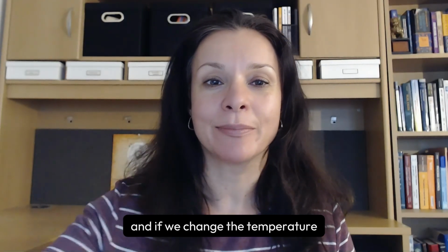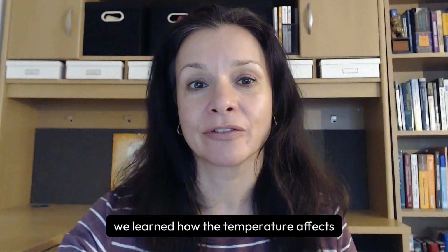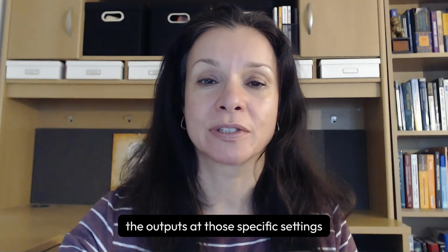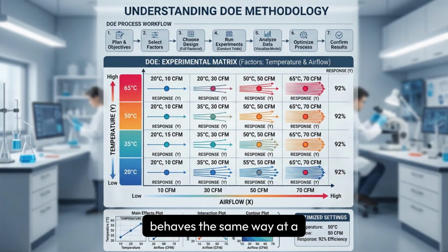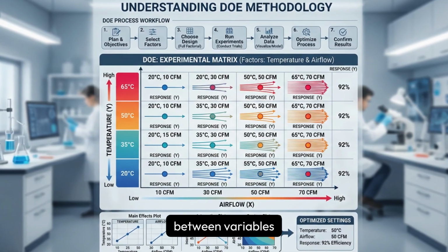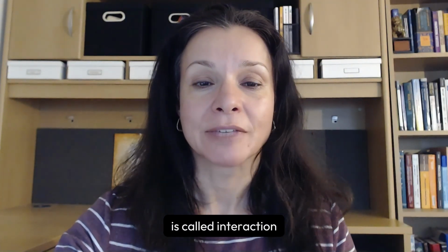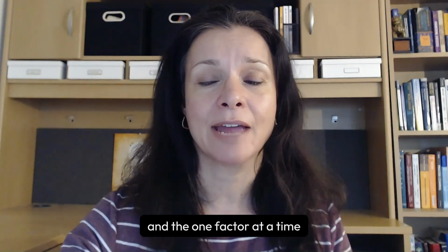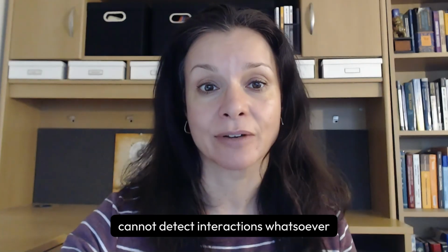And if we change the temperature while holding airflow and speed constant, we learn how the temperature affects the outputs at those specific settings. But we have no idea whether the temperature behaves the same way at a different airflow setting. So that relationship between variables, how the effect of one variable affects another one, is called interaction. And the one factor at a time experimentation approach cannot detect interactions whatsoever.